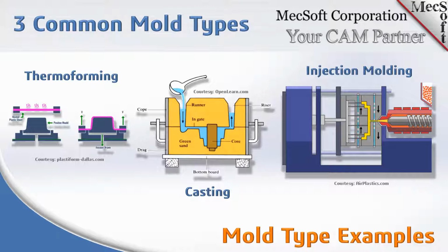Now, the third technique we're going to show you is the protection surfaces. And by protection surfaces, in our example insert, you see that we have added extensions to the cavity surfaces, and we have added extensions to the parting surface of the mold. So here on the parting surface, you see that it extends out past the mold on each side.